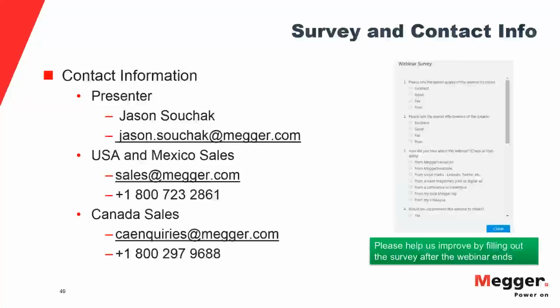Do you have any PD test equipment, or does Megger have any PD test equipment, to test 72 kV rated power cables? Part two: do you also have any equipment for VLF testing of high voltage cables? Okay, so yes, we have equipment like that. Just to clarify, we have DAC technology for medium voltage cables, and there is DAC technology for high voltage transmission cables.